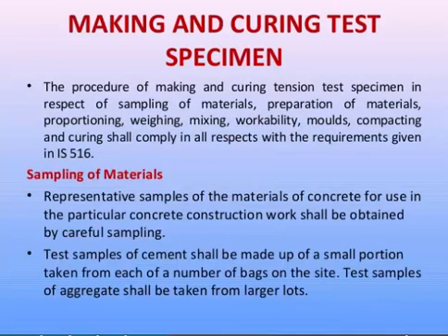So we have discussed the apparatuses and the general procedure of this test. Now students, when the mixture is prepared, it is poured into the oiled mold in layers approximately 5 centimeter deep, as I have explained to you. Then each layer is compacted either by hand or by vibration.